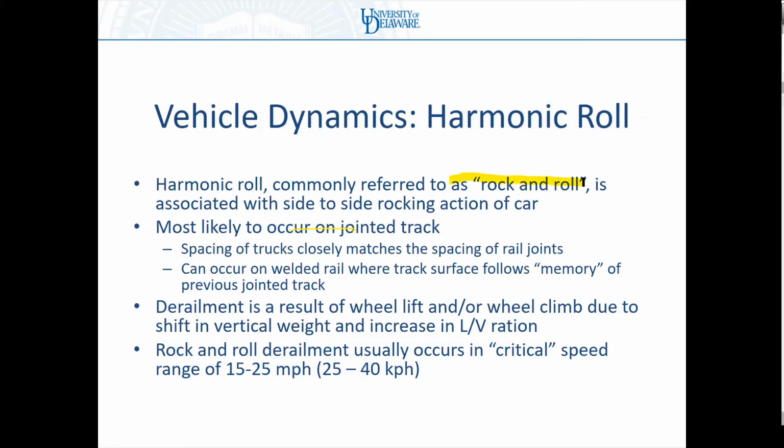So harmonic roll or rock and roll, which is that side-to-side rocking of the car. Now, it most likely occurs on jointed track, but it does occur on welded track where you have a series of battered joints. Again, this is the case with battered welds. So this is the case where either the joints or the welds are staggered, which is a common design in the heavy axle load world in particular.